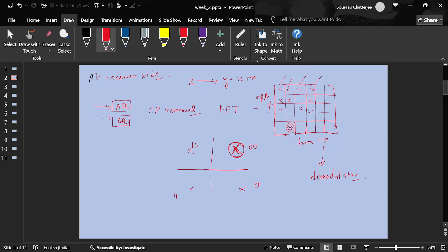Noise. At what end? Transmitter end or receiver end? Transmitter. And what is the source of that? It is introduced in the channel. Okay, so yes, your AWGN channel model, additive white Gaussian noise, is being added. So why do we call it Gaussian, by the way?